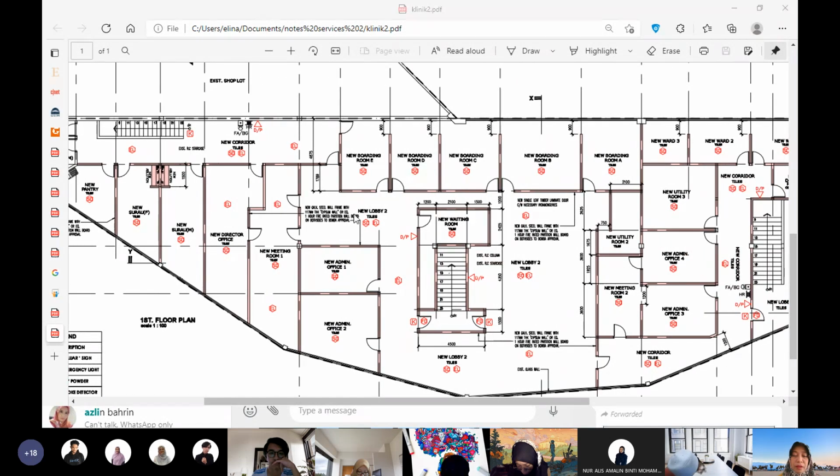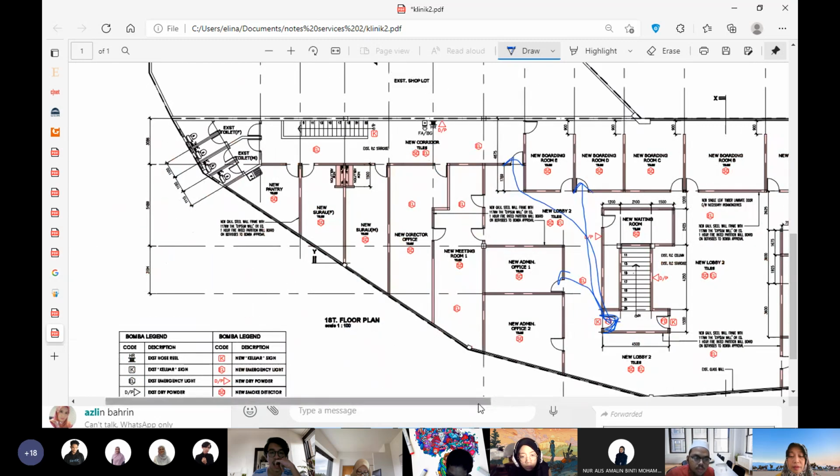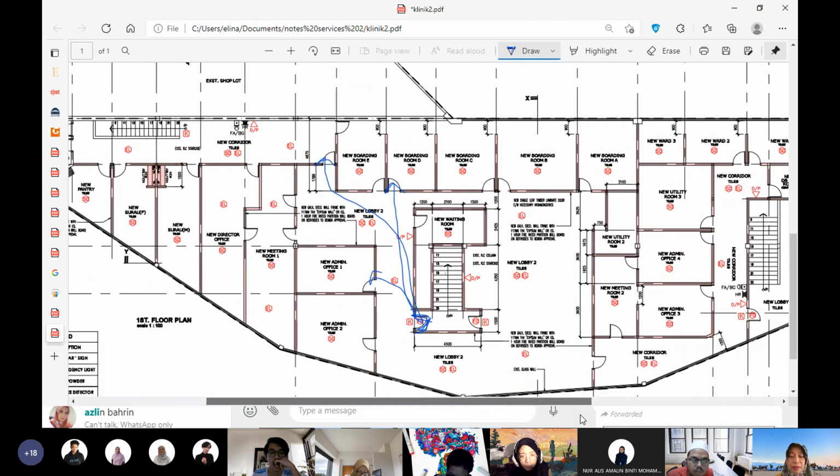So the difference is the distance to the fire staircase. I draw the fire staircase here. FD is the fire staircase. We are using the legend, from the door of this room to this back room, they must meet a certain dimension.